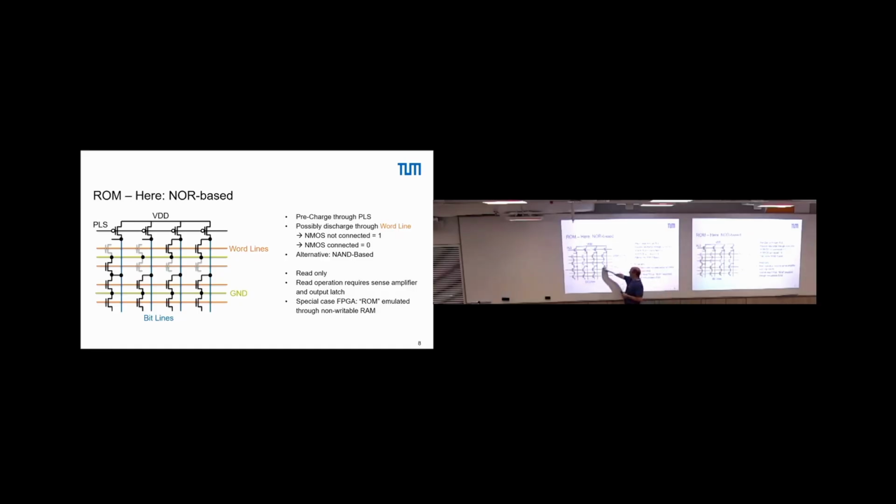But here now, for the other word line, we have no connection. So if we pre-charge here to VDD, open the switch so that only the capacitance here holds some charge, and then activate the word line, nothing happens. If we read here, there are charges on this capacitor, built by the wire. So we would switch to a 1.